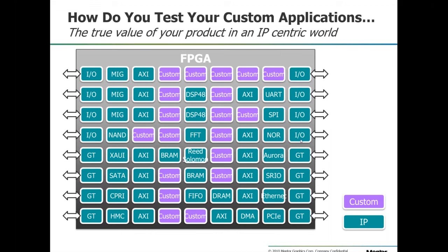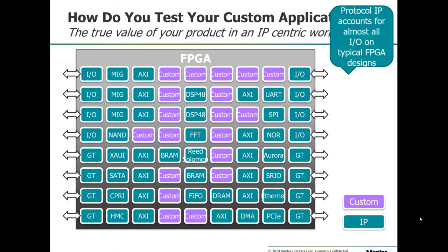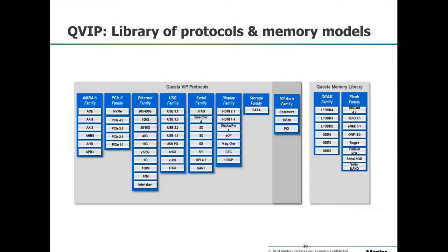But as you go out to the I/O coming into your thing, it's probably standard things like UART and Ethernet and PCIe and SATA and all these other standard protocols like AXI. And so you're pushing data through these standard protocols, and Mentor provides a library of different standard protocols that are basically UVM agents to allow you to do that.